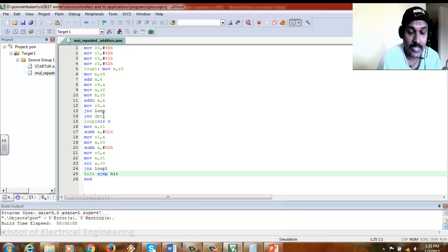So here I have used this DPTR because, as I've already told you, this is 16-bit multiplication. You are supposed to get 32-bit. To get 32-bit, this DPTR happens to give a consistent result, because other registers are all 8-bit registers, but the 16-bit register you can manipulate using this INC operation. So that's it. This operation will happen again and again until 4532 goes to 0. So 4532 we'll have to decrement.